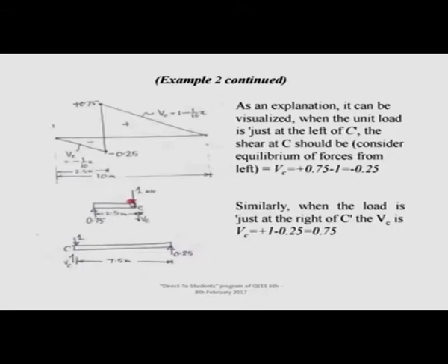So, it says I have a downward force of 0.25. Definitely, according to your sign convention, in the influence line diagram you must plot that shear as negative, so this is plotted as 0.25, that is why it is negative. You can see the shear force diagram, and you can see the influence line for shear force at this location, and now you can digest that.